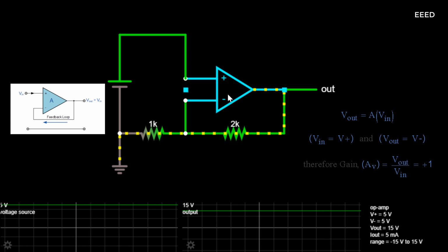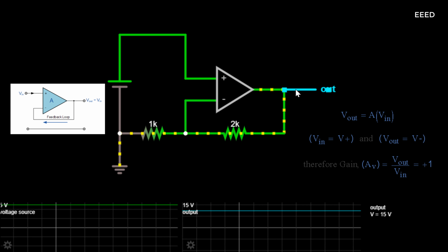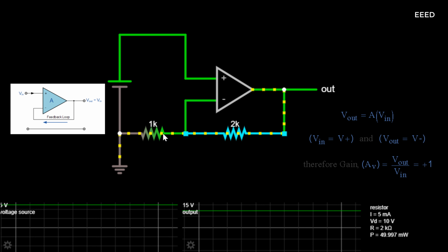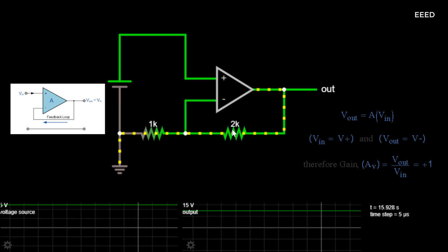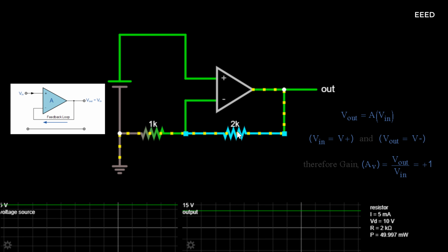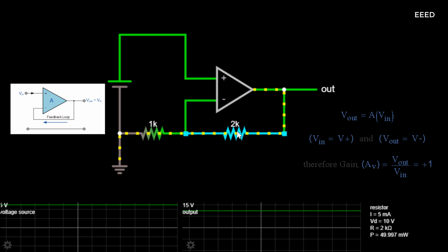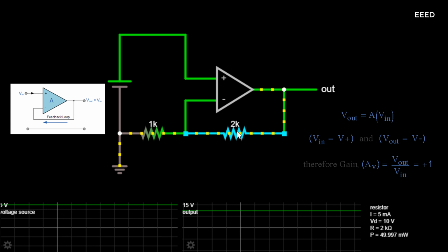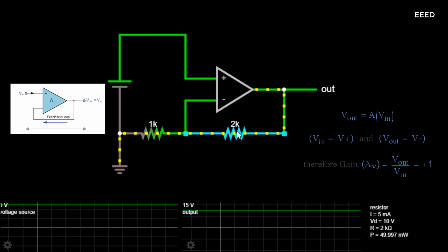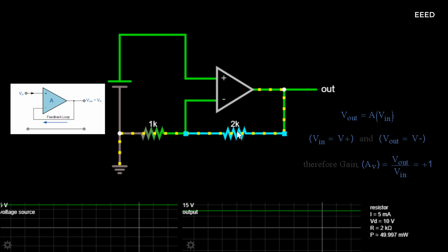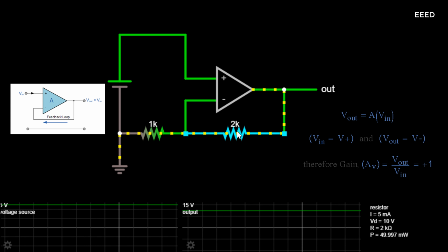Thus far we have analyzed an inverting and non-inverting amplifier circuit that has just one input signal, VIN. In the next tutorial about operational amplifiers, we will examine the effect on the output voltage, VOUT, by connecting more inputs to the amplifier. This then produces another common type of operational amplifier circuit called a summing amplifier, which can be used to add together the voltages present on its inputs.